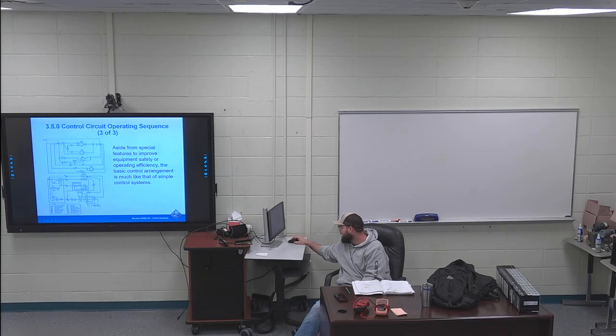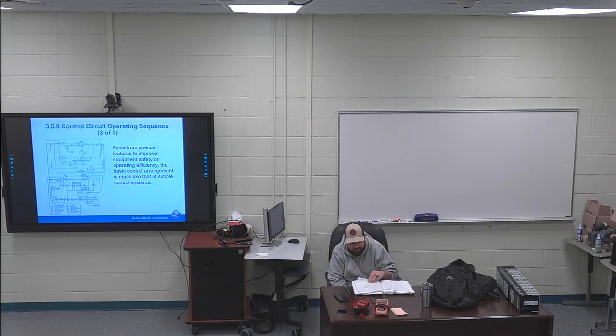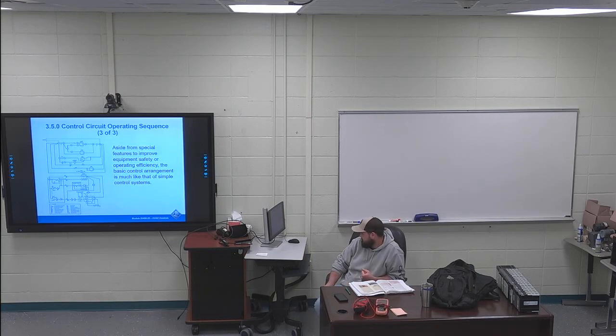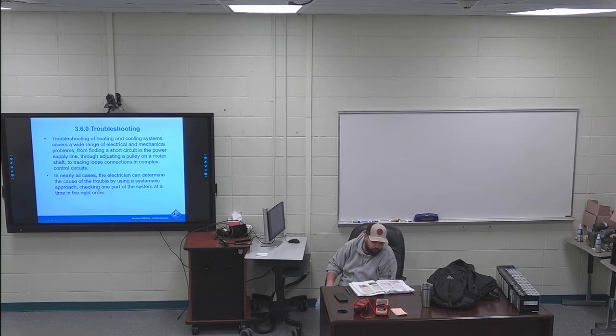IDR is going to turn on my IDM. If I look at what my IDM is, that's my induced draft motor. That's my inducer motor. So that's the first thing that's going to happen when I turn my thermostat to heat. That's something you should know. You should know how to read through that schematic. I would read through that section on how to read through that schematic for sure, if it doesn't already make sense. By this point, you should know how to read that in electrical 4.